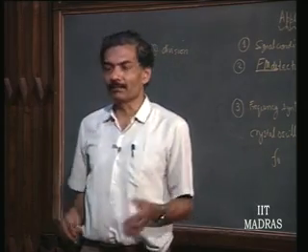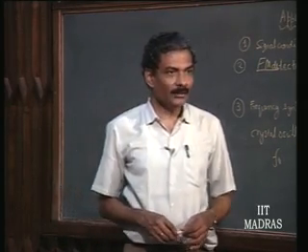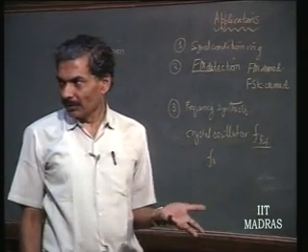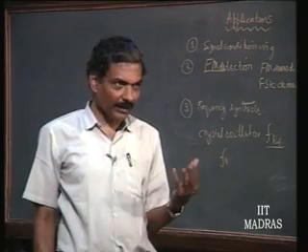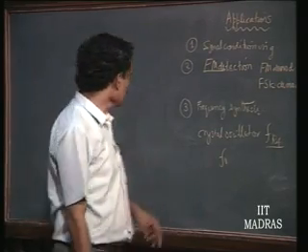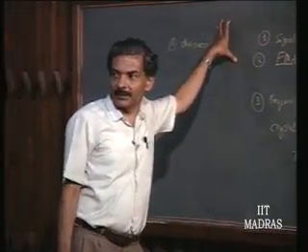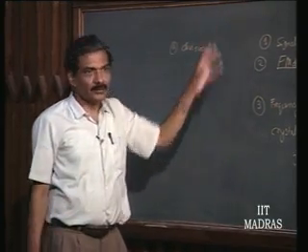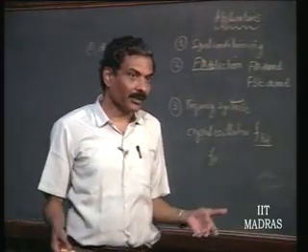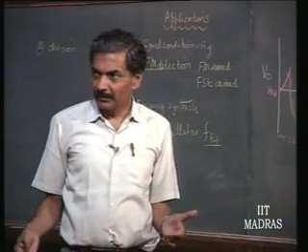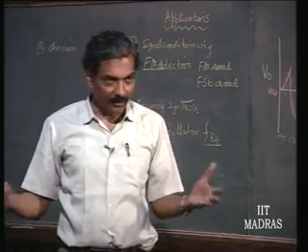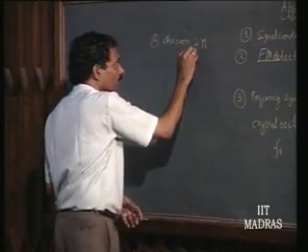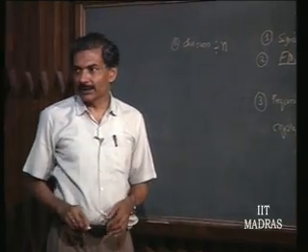Division by 2, for example, binary division is done by a multivibrator, right. You know. So, very simply you can do division by a factor of 2 by using digital circuitry, no problem. So, division by any number can be done again by using counters, right, any integral number, right, integer. So, division by any number n can be done using digital circuitry.